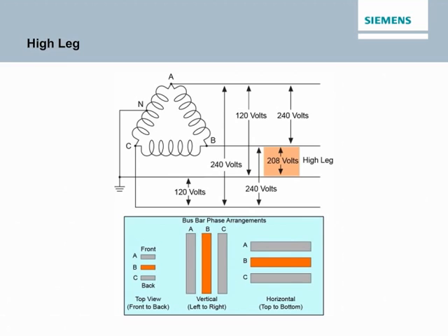NEC Article 110.15 requires that the high leg conductor or bus bar be permanently marked with an orange finish, or by other effective means, at a point where the connection is made, if the grounded conductor is also present. In addition, NEC Article 408.3(E) states that the B phase should be the high leg. NEC Article 408.3(E) does permit some exceptions to this rule for existing installations or metered service equipment. Refer to the article for details. More information on calculating the value of the high leg, as well as connecting loads, is discussed later in the course.